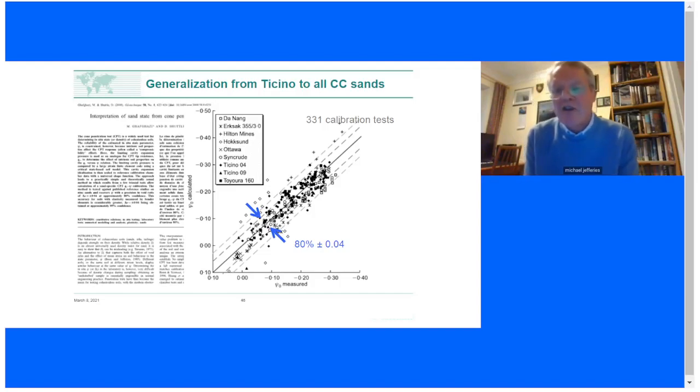So you're looking at 331 calibration chamber tests in here. They report a void ratio, and these people shared their sands with us. So we've tested the critical state loci, so we can convert their void ratio to effectively a reported state parameter. And for each of those runs, they report a QC value.